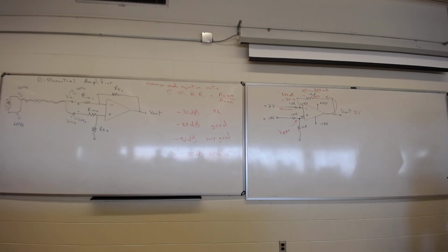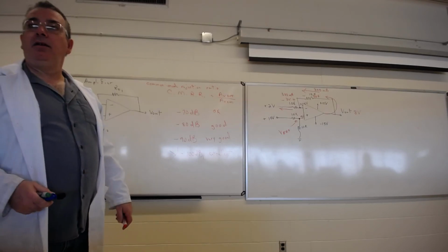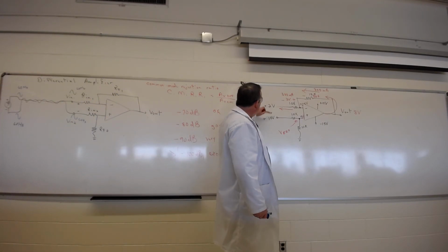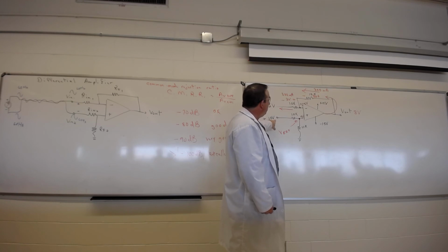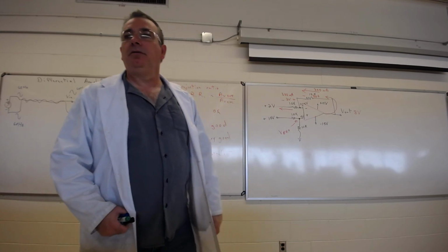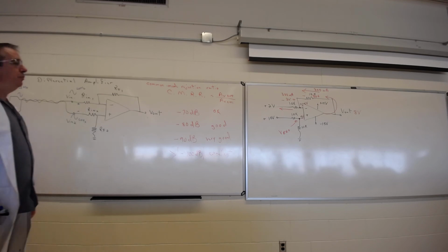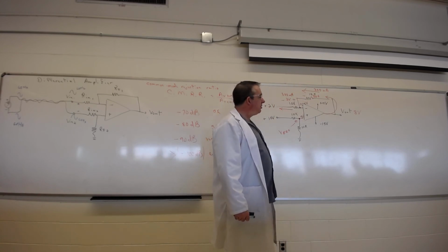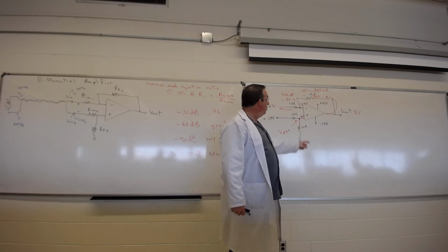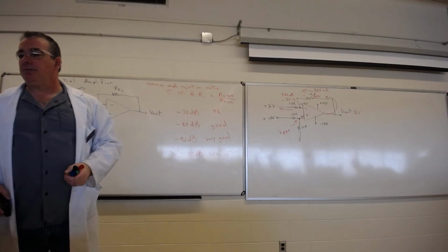And if you take a look, our amplifier, 10K and 10K, had a gain of 1, and the difference between the 2 inputs was 8 volts. And the positive side was bigger, so we've got 8 volts at the output, positive. Works like a charm. Is that right? That's a differential amplifier. So you can put 2 voltages into this thing, and it gets amplified, out it goes. It works the same way as everything else. The trick is calculate this reference voltage, and then you know what the voltage is on the other side. All right, so that's our little thing on amplifiers. Okay?